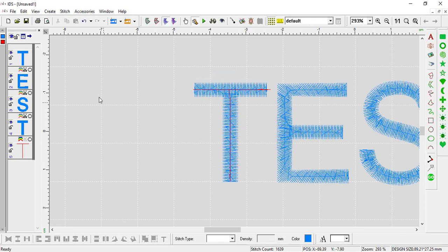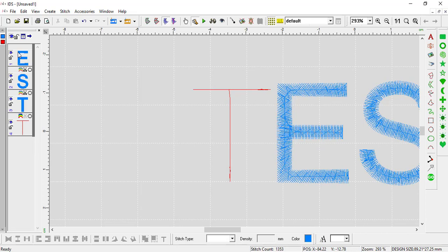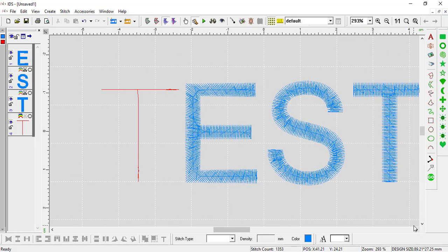So with that line stitching on top, I can delete the area. On the left hand side, I can see my stitch sequence viewer. I can left click on that area and then hold down the control key on my keyboard and then hit delete on my keyboard. So now that area is gone. So that is with the Create Freehand Line.